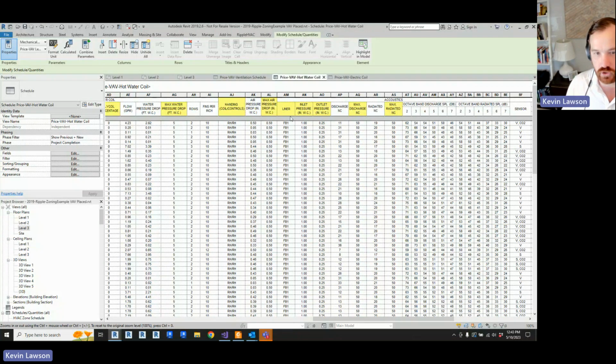Your actual noise criteria comes through. So here's what the maximum was set at, based on the input. Here's what it actually came out to. And this is kind of why I know that if you set your pressure drop reasonably, you're not really going to get close to your discharge NCs. And then all your octave band information is in there.